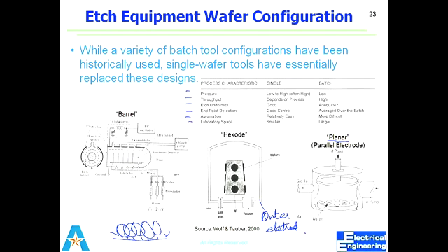As an example, I have taken that the endpoint will be more efficiently detected in single wafer processing as compared to batch wafer. So due to these benefits of the process characteristics, we are moving towards single wafer processing as compared to batch wafer processing.